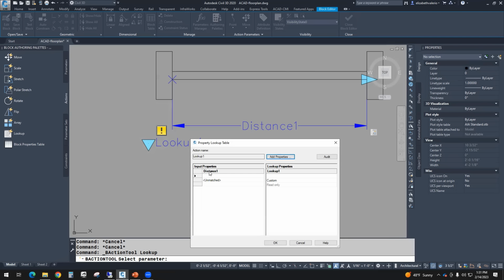So here distance 1 shows up. When you click on distance 1, there's a drop down and you can pick 2 feet. And then if you click below the 2 feet, you can use a drop down again, pick 3 feet. So we're just filling in all this information that came from the properties. This is what your window will look at to fix the size of the window.